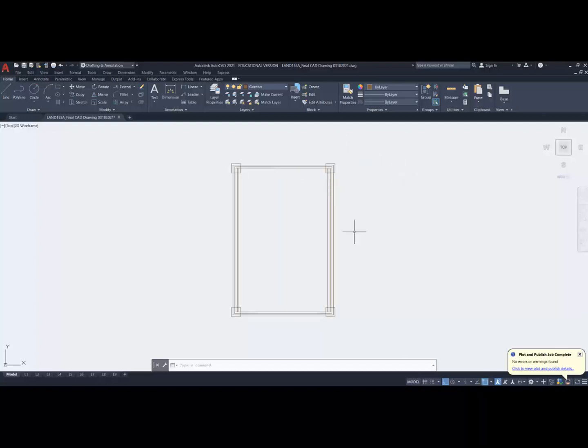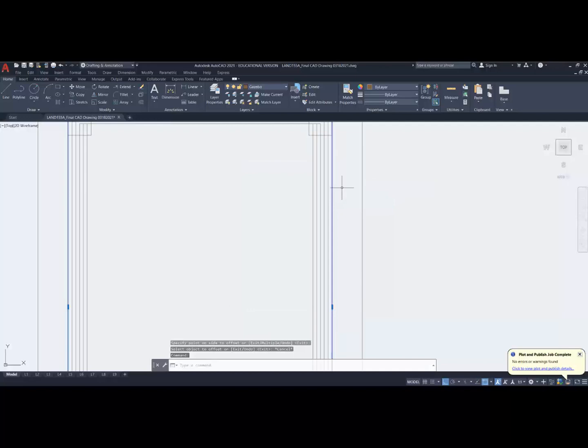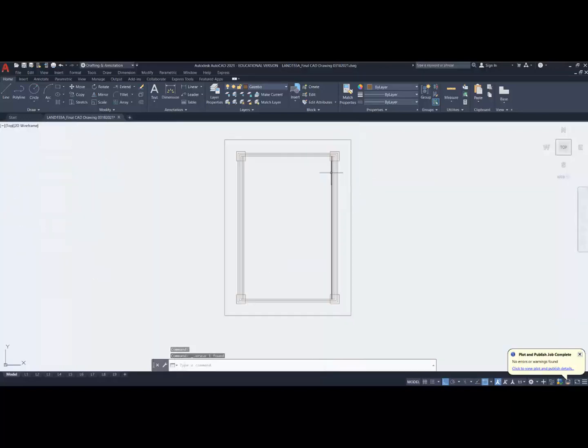And I may want a 1-foot overlap or a 2-foot overlap. So I'm going to create a rectangle. And this overlap is typically called an overhang. So offset 12, taking this outer line, offsetting it 12. So I'm going to have a fairly smaller shape overhang roof, and I can have up to 2 feet from the center line of the post where it supports.